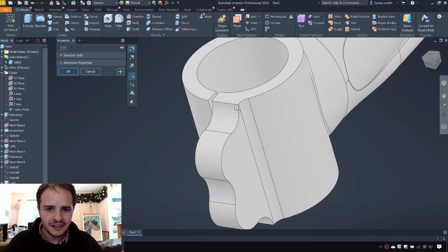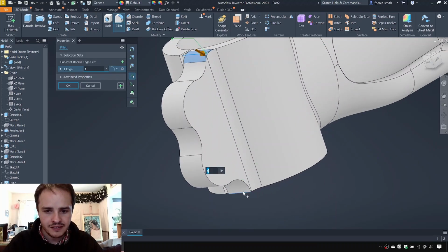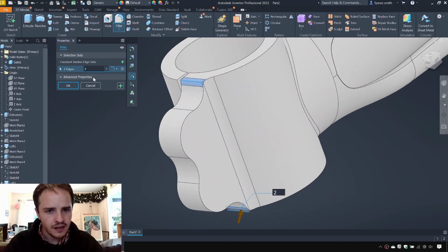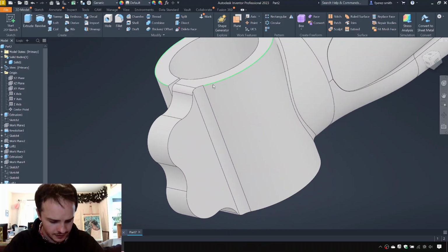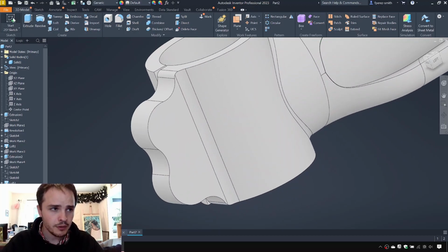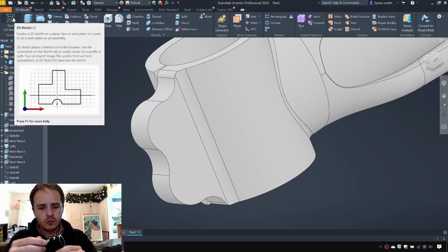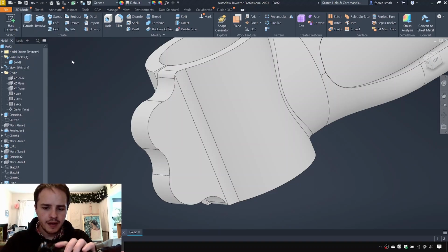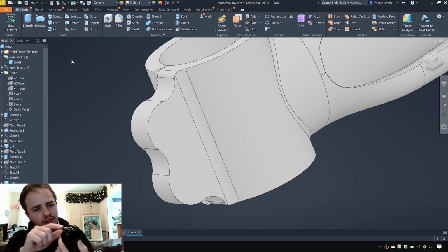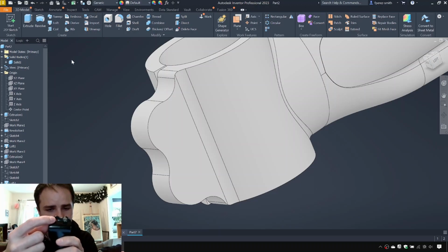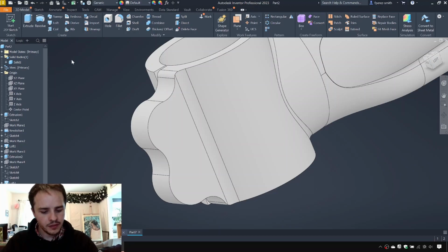And we might also add in some more fillets on the top and bottom. So we might say top and bottom there. Let's go ahead and add in a 2mm fillet will do. Lovely, looking good. There might also be other fillets, but we'll add those in after. So what we want to do next is put the holes that go through here. Now, if I take out this bolt, I can see that it's not only the same bolt as before, but it's also got the same internals. So we've got a counterbore in here and threading on the other side.